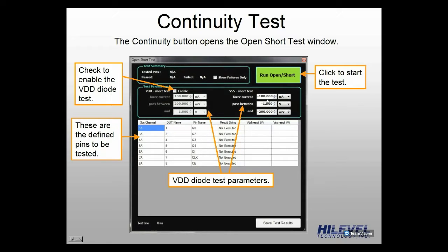Most devices have a built-in ESD protect circuit, which includes a diode connected between the signal pin and ground. Other devices have two diodes, one between the pin and ground, and the other between the pin and the power rail. But not all devices have both these diodes. Some pins will have two diodes, some have one, and others may not be ESD protected at all.